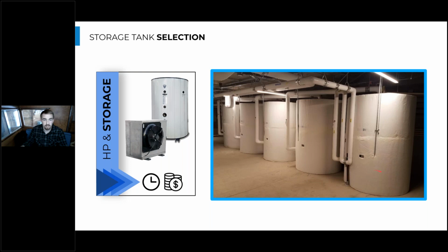So that's why we have this big series of marshmallows that are our storage tanks: we want to make sure we have enough capacity, as well as giving those heat pumps enough time to fill all that storage so they run a really nice long time. And it takes them a while to settle out after they turn on, so then they're seeing the most efficient conditions they can.